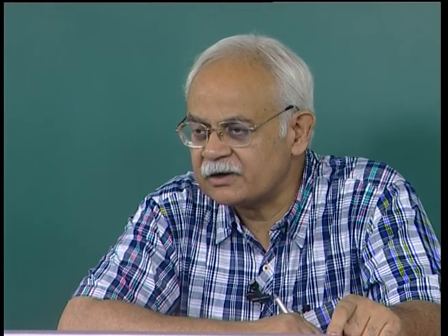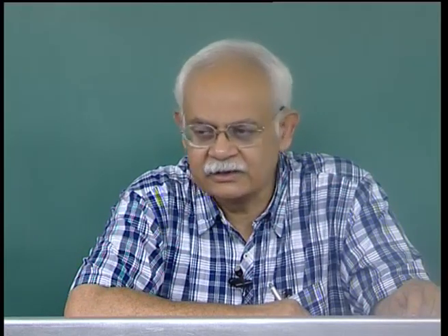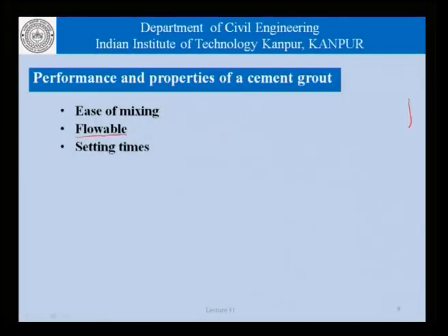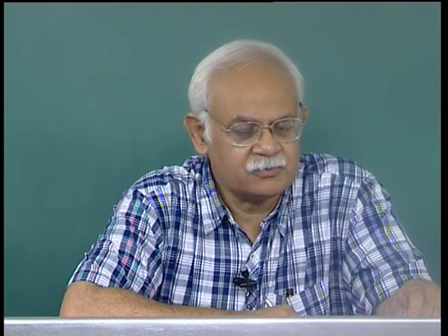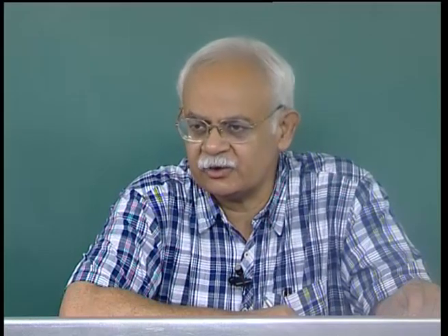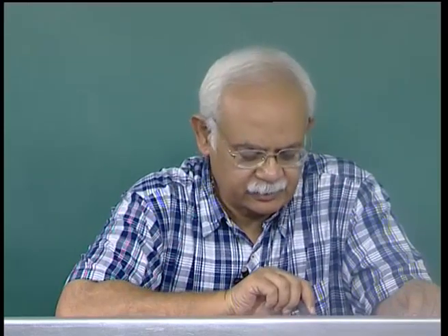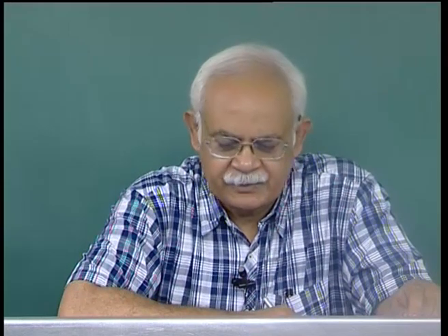At the same time, if the grout is not having a flowing consistency, it would be difficult to even use normal pumps in the construction process. Another property for the grout which would be of interest to us is the setting time. Like all concrete construction, the grout, once it has reached its final location, we would like the system to set, and therefore, the setting time is of great importance as far as grouts are concerned.